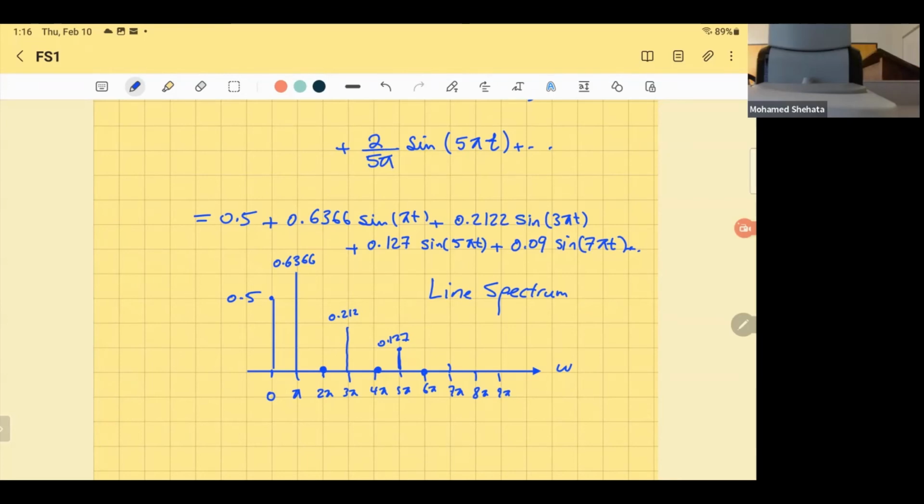So you know, okay, when I design the filter, of course, you want to get rid of this, right? This is the vertical, what you wanted there. You get rid of this, and this. This is small, so I'm not going to design it for this one component. It's just enough if I get rid of the third and the fifth, that's good. The rest is negligible, very small. So you look at it and see what's happening, and then you design the filter.